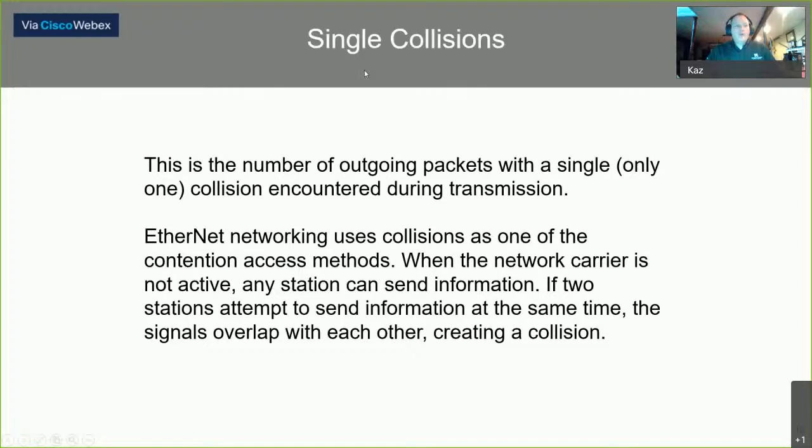So there are 4 collision counters in the EN2TR that we were looking at. In general, in the past, collisions used to be okay, because in the past we had things called hubs. They were basically 10 meg half duplex hubs, and hubs are bad. You shouldn't be using hubs. If you have a hub in your network somewhere, you should disconnect it, replace it with a switch, take it out and start a bonfire. Don't cook over the bonfire because there's probably toxic fumes in there, but hubs should all be thrown away and burned. They're not useful.